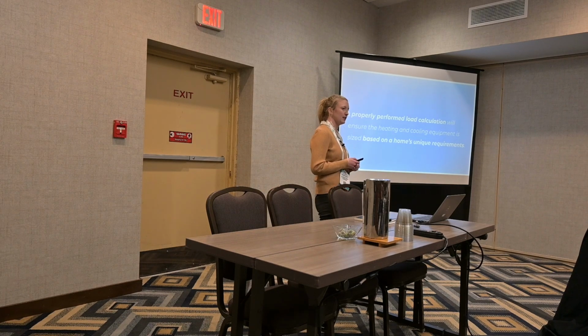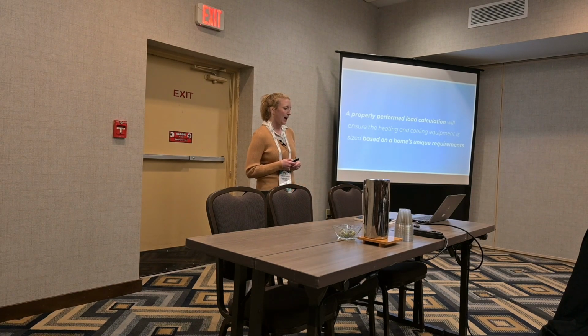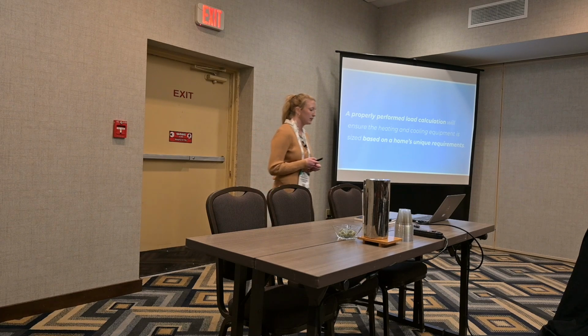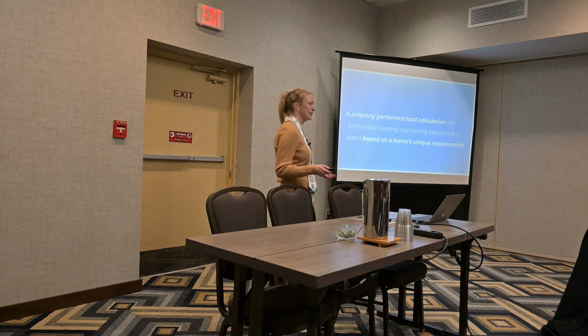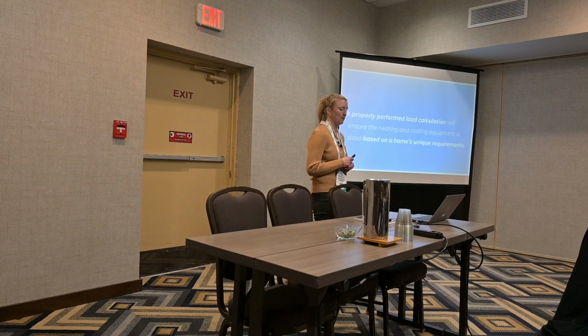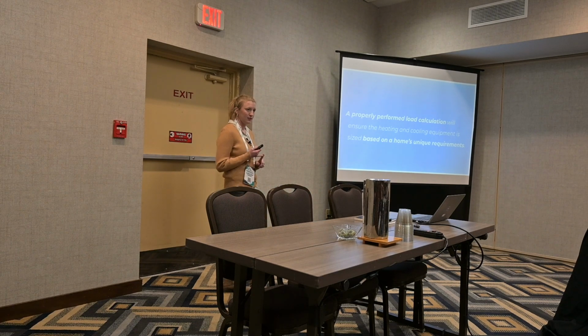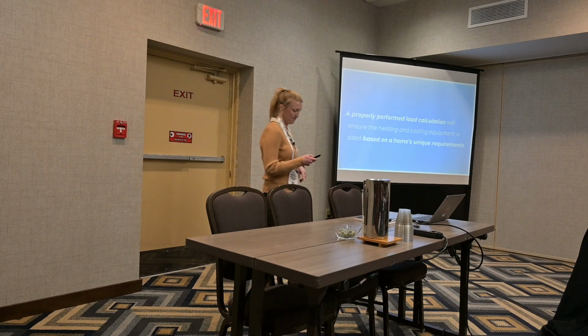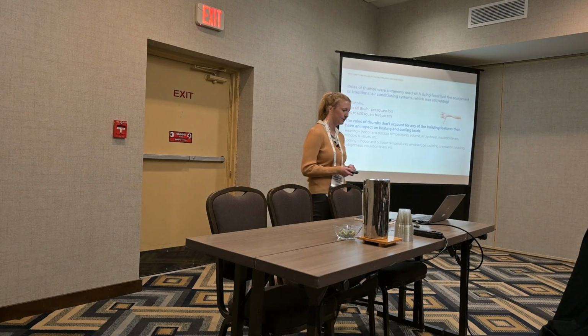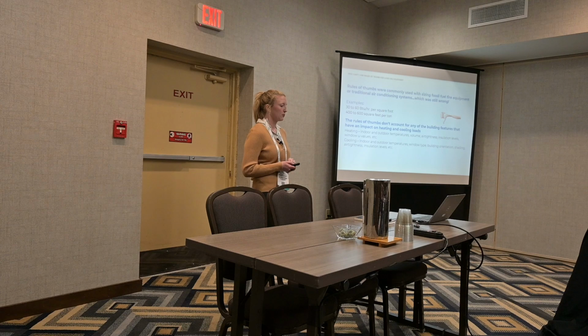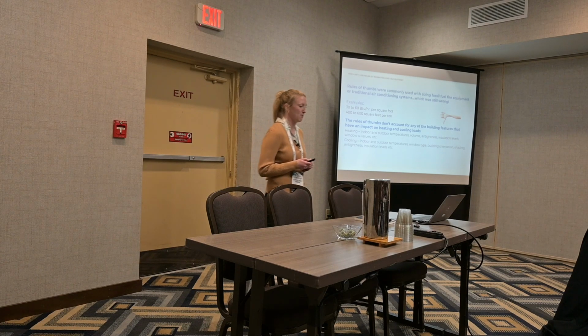It's important to understand that every home is unique, and a properly performed load calculation that accurately represents the home is one that takes into consideration all of its unique requirements. So what does this mean? It means that you can't use any rules of thumb. Rules of thumb should especially not be used to size heat pumps.